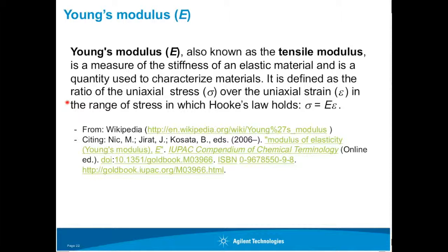All right. Okay, so that's Young's modulus, and that is one of the material properties that we get from instrumented indentation. And you can see just from this relationship why Young's modulus is so useful. If you're designing with a particular material and you know its Young's modulus, then you can predict stress for a particular strain. If you have strain and you know the Young's modulus, then you can predict the stress. Vice versa, if you know what the stress in that member is going to be and you're in possession of the Young's modulus, then you can predict the strain in that member. And so from an engineering standpoint, the Young's modulus is an extremely valuable design parameter.